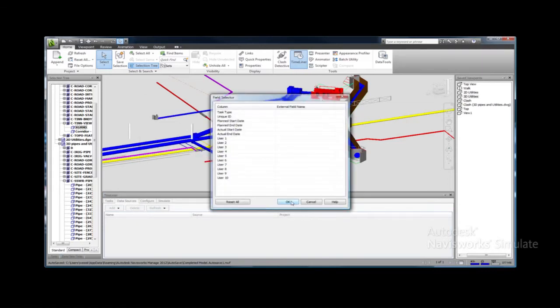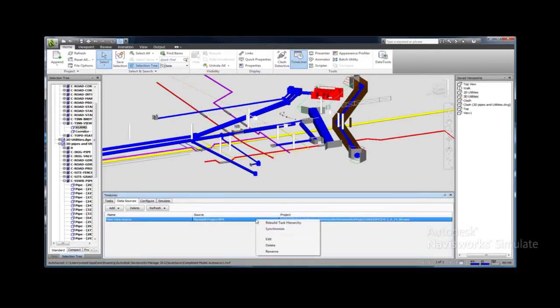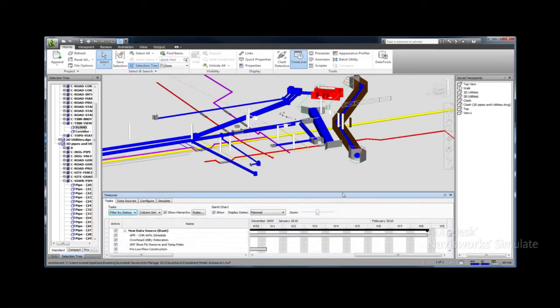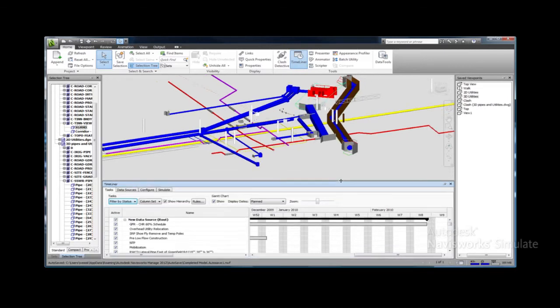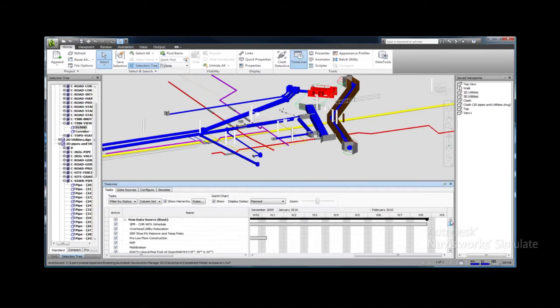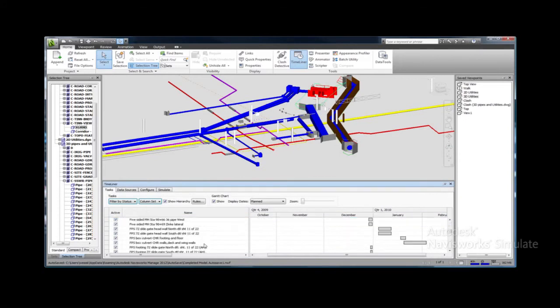Let's see how Navisworks can be used to visually simulate construction processes and perform 4D sequencing to confirm our proposed construction schedule. In Timeliner, a schedule your contractor has prepared in Microsoft Project can be accessed directly by Navisworks. Once imported, a Gantt view of the schedule can be examined to view tasks scheduled with respect to each other. Once the tasks have been imported, model objects must be associated to the various tasks such that we can get a visual simulation of the construction schedule.